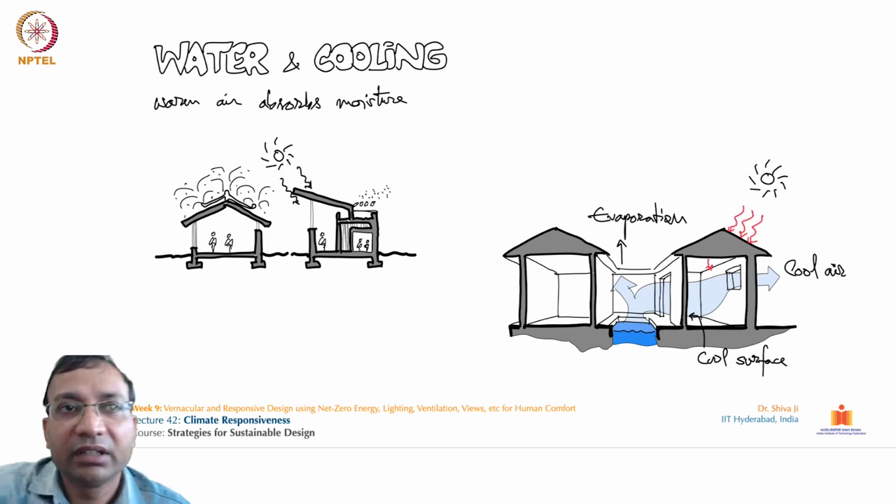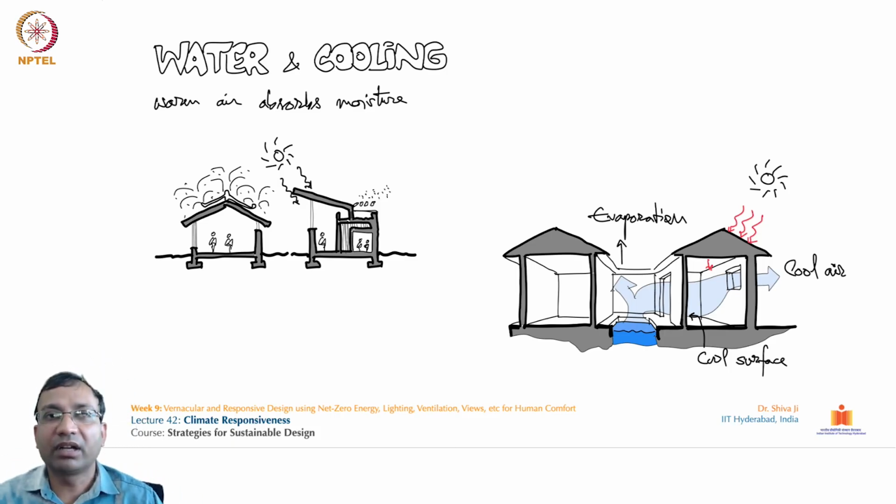Similarly, for the water and cooling effect, how these pergolas and other sunshade devices can be installed in which parts of these buildings, and how this can be maximized for efficiency. You can see here this double roofing treatment is given, to minimize the overall heating in the bottom floor. So there is a buffer area of air only, because air is one of the best materials for thermal insulation. So this air is also naturally trapped over here, creating a buffer zone.